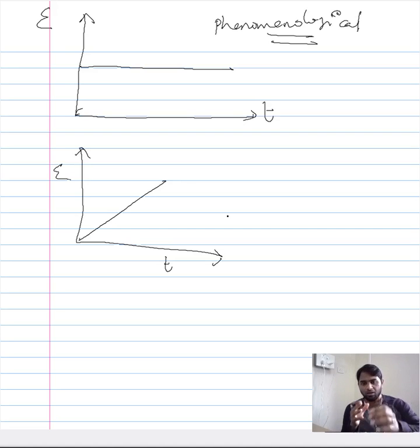So far, just to give a conclusion or summary of this lecture, what we have seen is that there is a characteristic curve by which creep behavior can be represented. If you want to represent the creep behavior of a crystalline material, you can do it through a characteristic curve, and just by considering the slope of the different regions in this curve, you can section it into different stages.